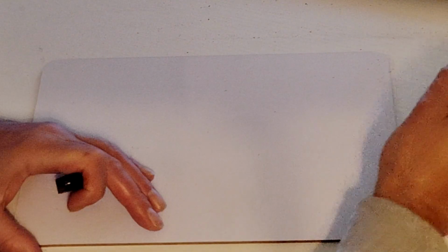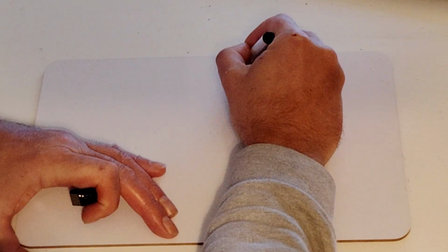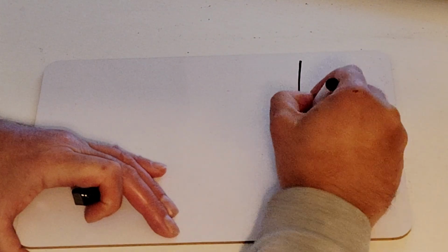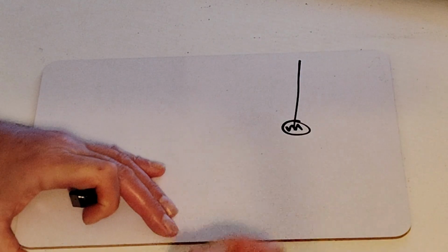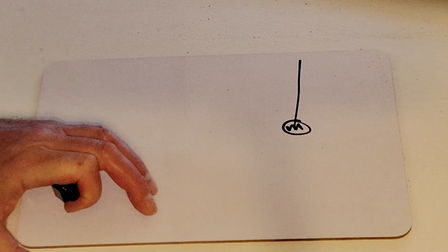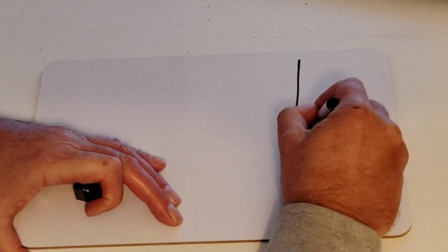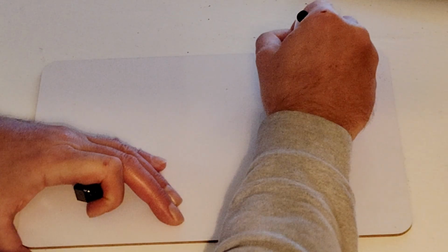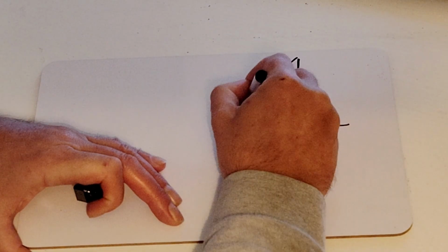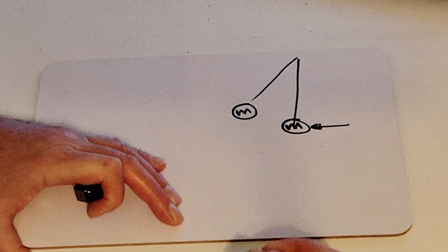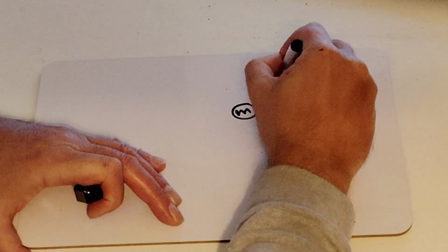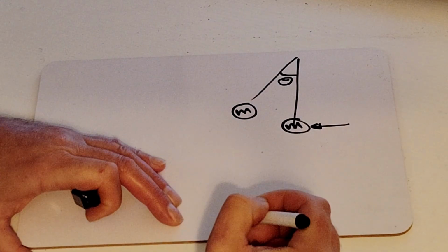Okay, so we're now going to try and establish what the post-impact velocity of the bag was. Now, the way which we can do this is we need to model the bag as a simple pendulum with mass m, and when an impact happens to one side from the punch, it will be displaced horizontally and vertically based upon an angle which we are looking to measure, theta.